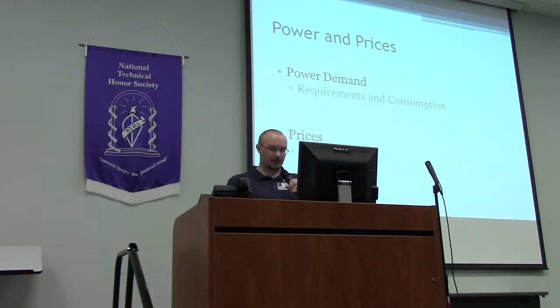While manufacturers of high-end video cards may recommend a minimum power supply of 500 watts in a computer, a power supply of at least 750 watts is typical in a gaming computer with a single high-end video card. Providing adequate cooling becomes a challenge in such computers. Computers with multiple video cards may need power supplies in the 1,000 to 1,500 watt range. Heat extraction becomes a major design consideration for computers with 2 or more high-end video cards.